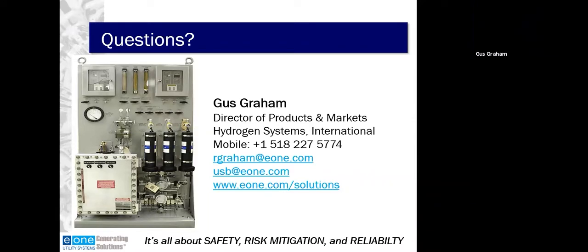And that comes to your second question, how frequently do you replace your moisture indicators? That's going to depend on the amount of oil carryover you're getting in your sample lines, which is a condition based on the design of the seal drain enlargement tank. GE has gone through several iterations of that over the years. Some machines are more prone to having oil carryover in the sample line and in the scavenging lines, and other machines have less carryover.